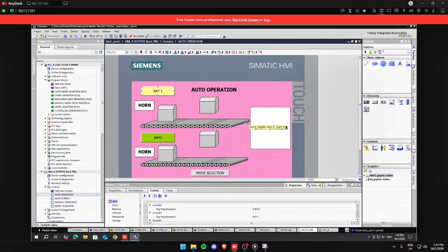To ensure precision, I integrate each detection logic, so the motor stops exactly when the part has passed through the light barrier rather than reaching it. So when this moves, the light barrier will turn on.